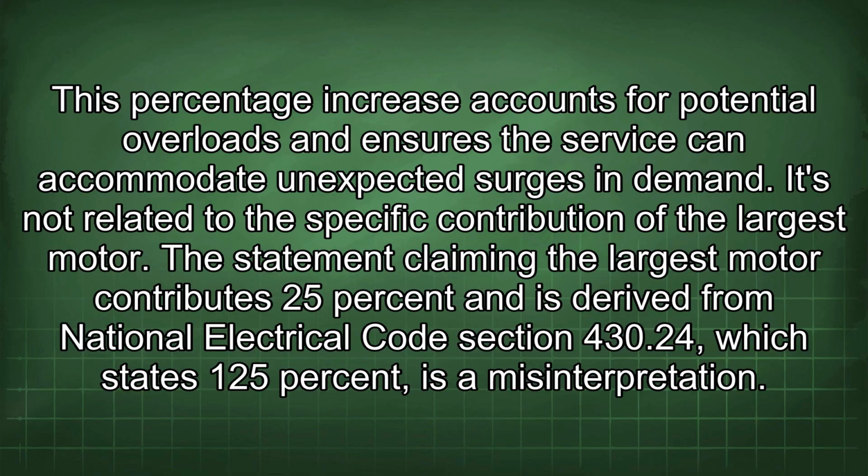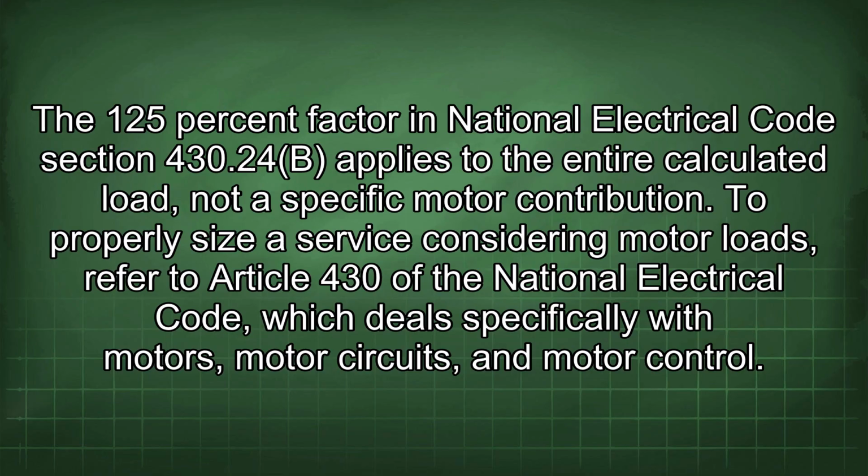The statement claiming the largest motor contributes 25% and is derived from National Electrical Code Section 430.24, which states 125%, is a misinterpretation. The 125% factor in National Electrical Code Section 430.24b applies to the entire calculated load, not a specific motor contribution.